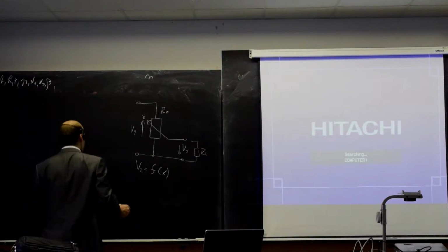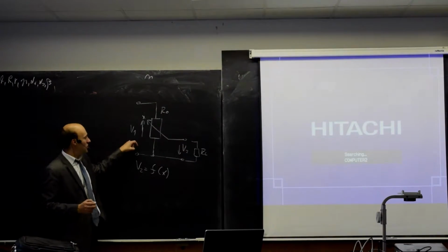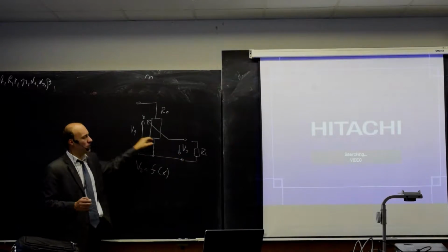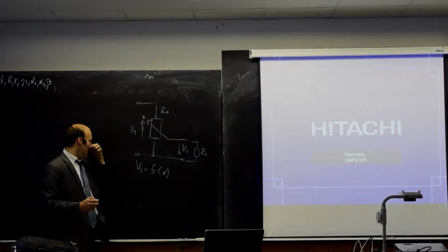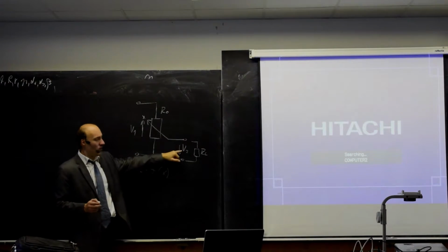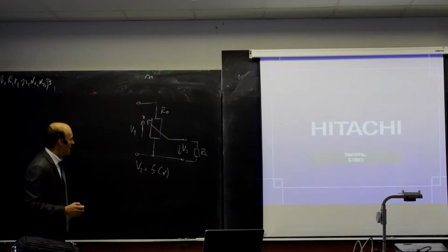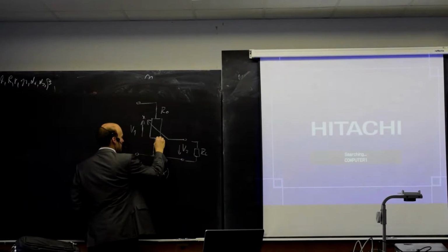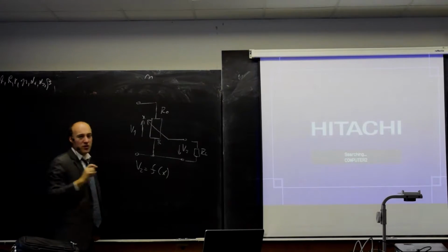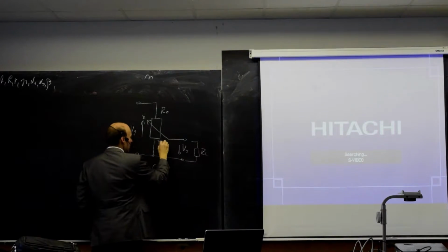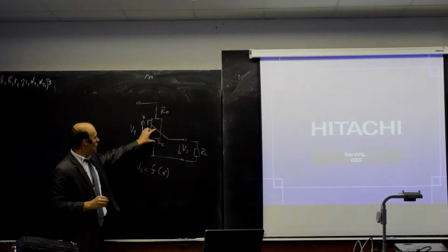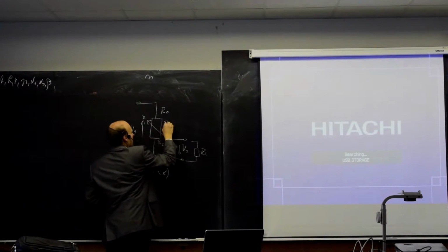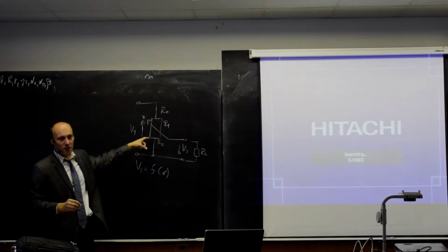So here the input voltage will also influence the output voltage. The bigger the input voltage, the bigger the output voltage. We could derive an equation for V2. In order to do this, we have to split this R0 into two parts. I will call this R2, and R2 is the section under the movable part, and R1 is the section above the movable part.